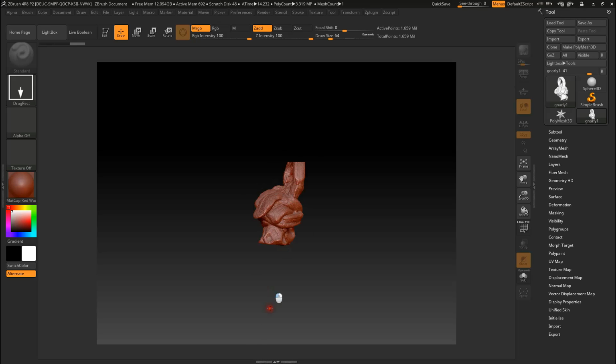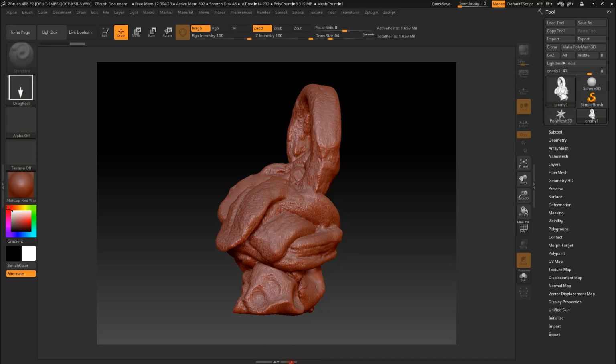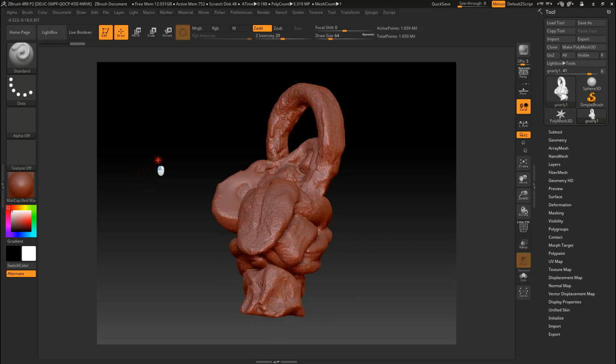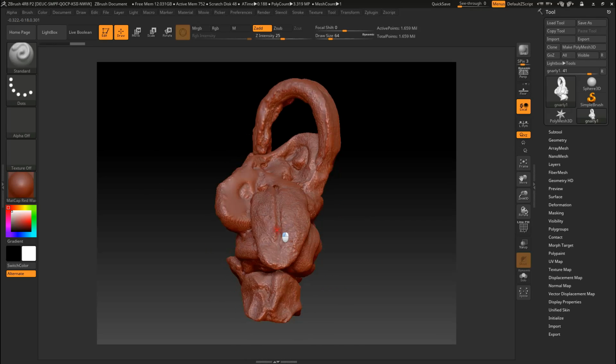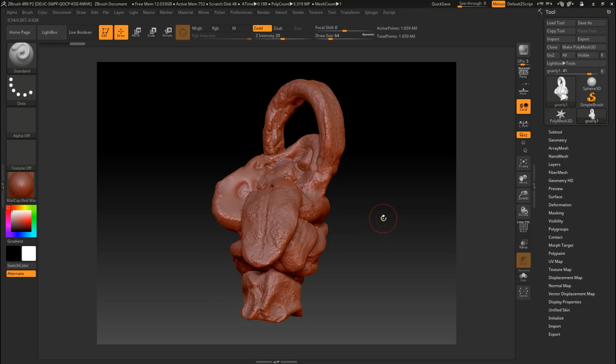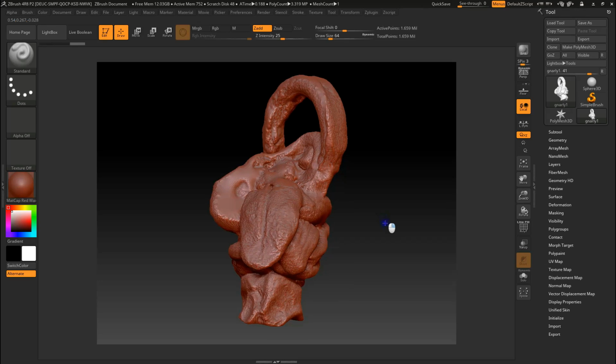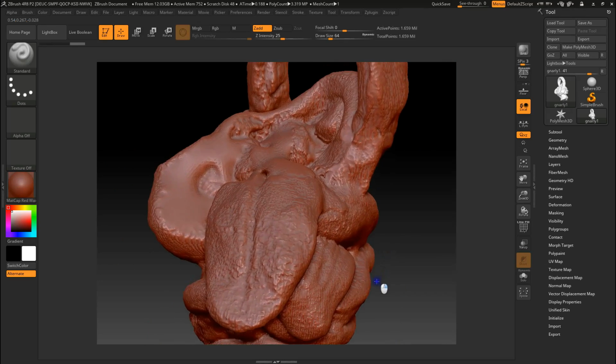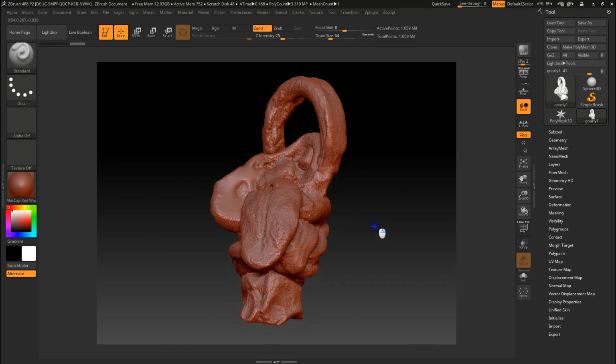What you actually have to do is draw one object like that, and straight away before you click on anything else you have to go into edit. And now once you're in edit mode and you click somewhere that's not the object, you can rotate it and move around it. To zoom in you have to hold Alt, right click and then release Alt to do that. Okay.